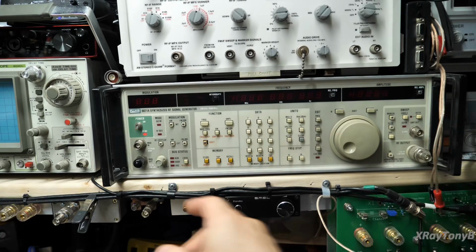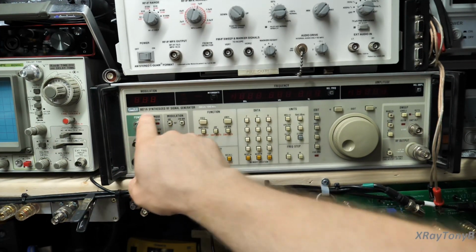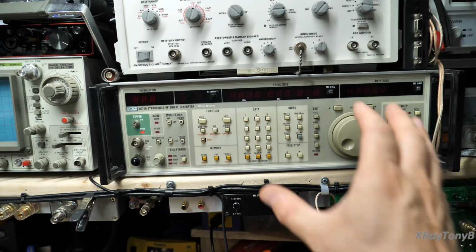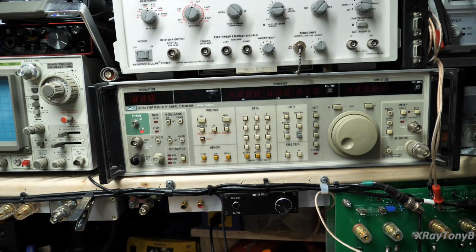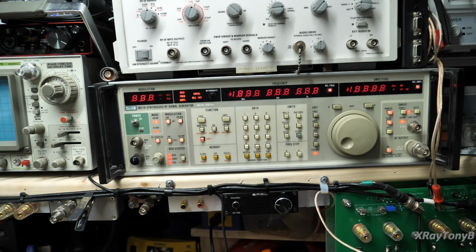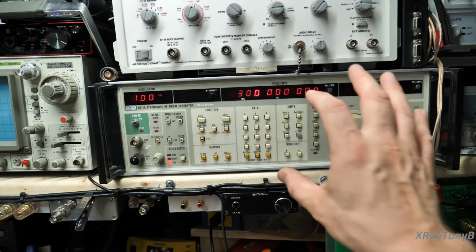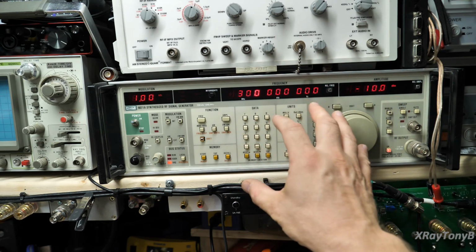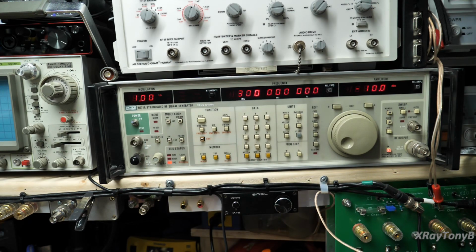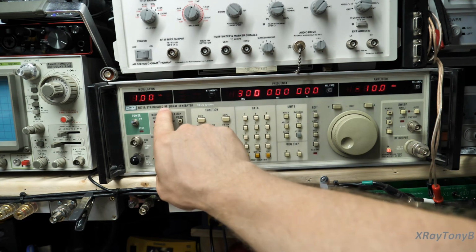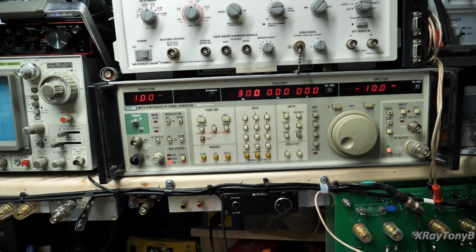Over here's another example. This is a Fluke 6071A, and it's the same thing as what you were looking at with the HP. It has a little different user interface, as you can see, and it does have a few more bells and whistles on it, but generally it is the same thing. It'll produce a carrier signal, and it will produce AM or FM modulation. And that's mainly what it's designed for. And it even tells you it's for radio frequency. That's what RF stands for.